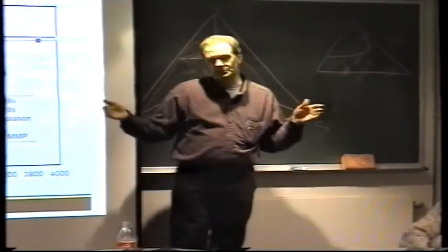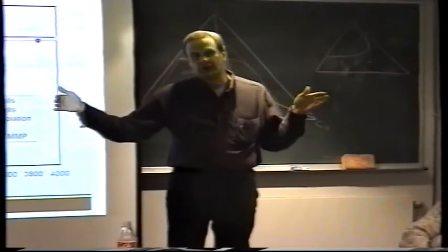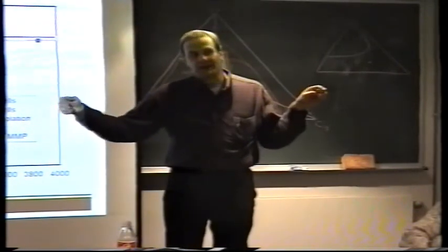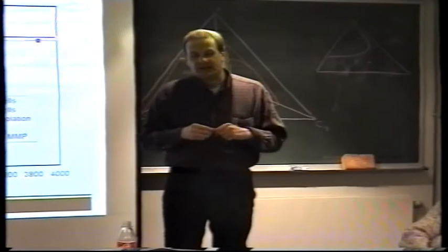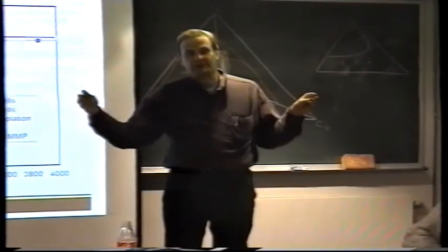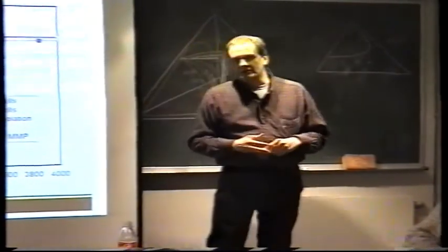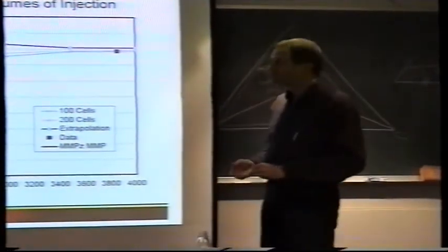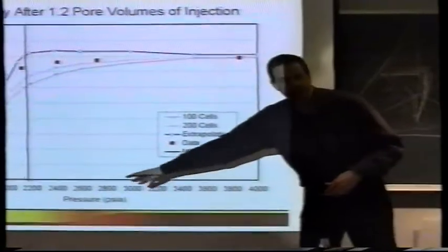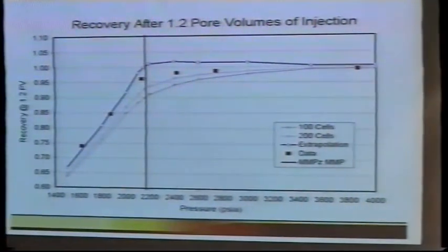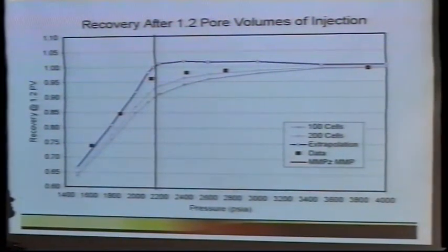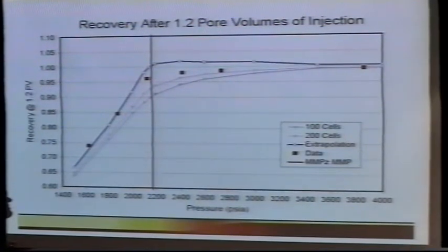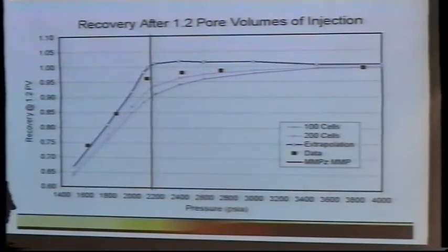It actually varies with time too, because when it's filled with oil, you get a larger pressure drop, and when you have mostly gas in the tube, you get a very low pressure drop. But it's on the order of 5, 10, maybe 20 psi across the tube, negligible compared with the average pressure.